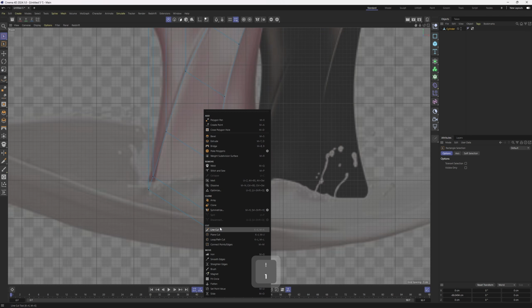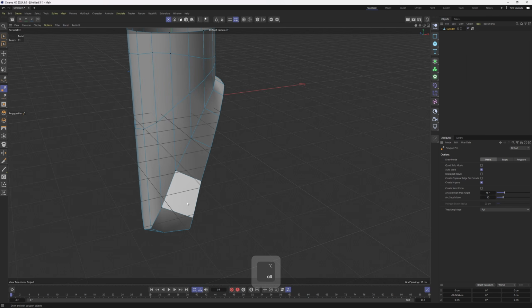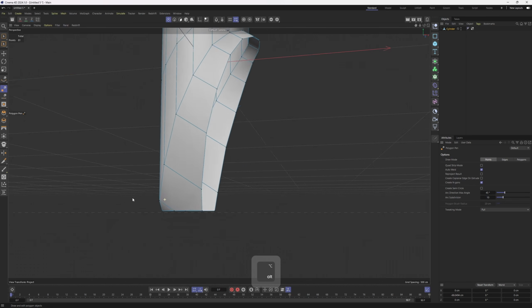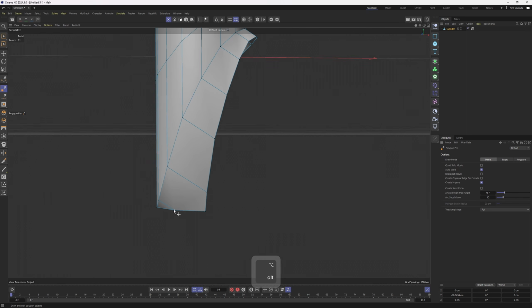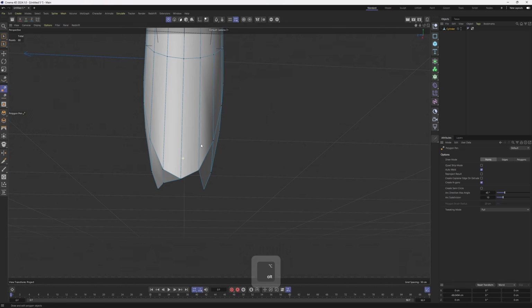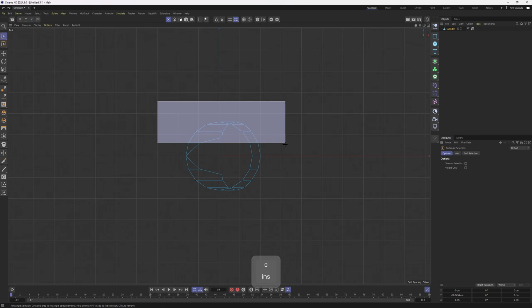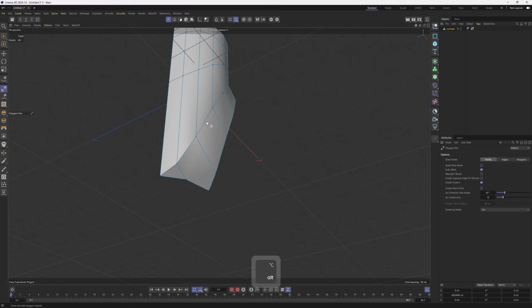Let's select this back, this section. The bottom part should be straight, so I will drop that cut in by holding Shift. Oops, one more time. Then delete these. Now I will grab polygon pen tool and try to fix the topology. By the way, we don't have to do everything twice, so I will just delete that side.